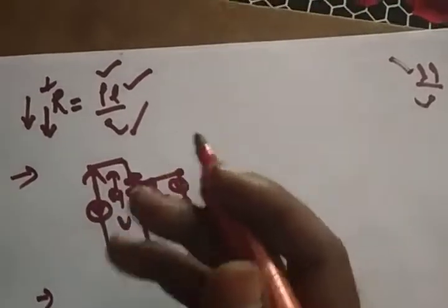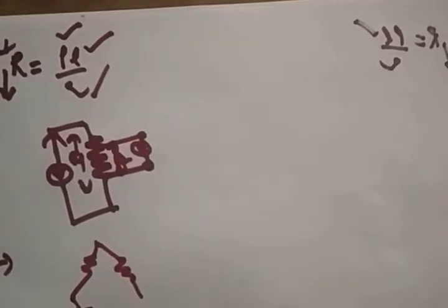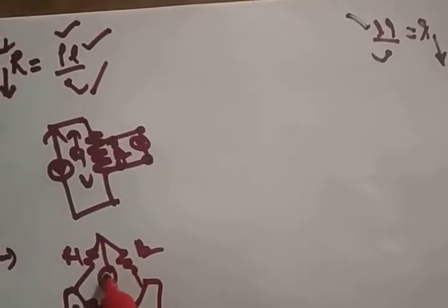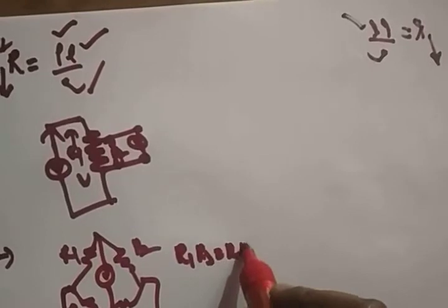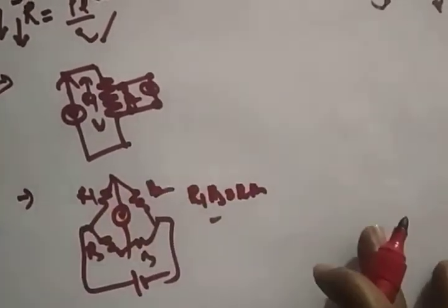After that we discussed the Wheatstone bridge, how it works, and what the formula is. R1, R2, R3. A passive transducer requires an external supply, and only then will these types of transducers work. This is a null deflection. When R1 R3 is equal to R2 R4, only then will the bridge be balanced and show zero deflection, 0 volts here.